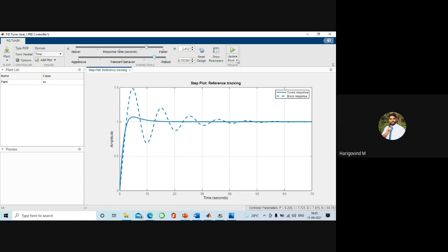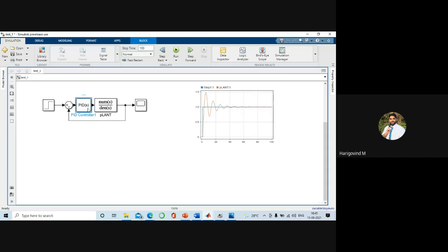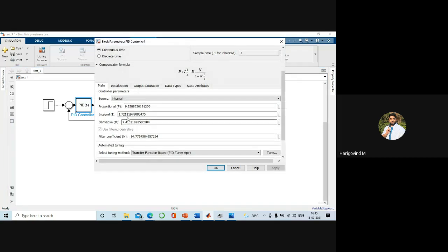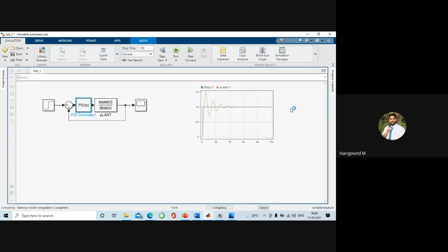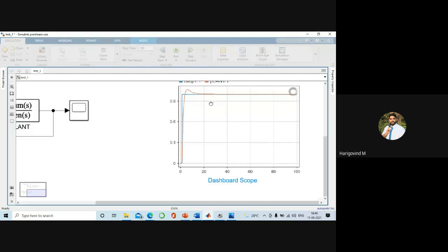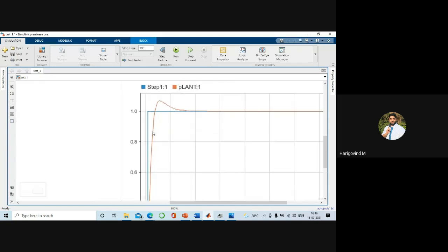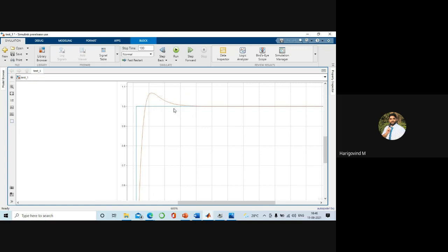So we can give update. Once we give update, the PID control values have now changed into the desired values. It is automatically changed. Now, if you run that, yeah, it is good. You can never get an ideal step signal, which is almost impossible. But there will be some transients. These are known as transients, and you can minimize the transients using PID controllers.